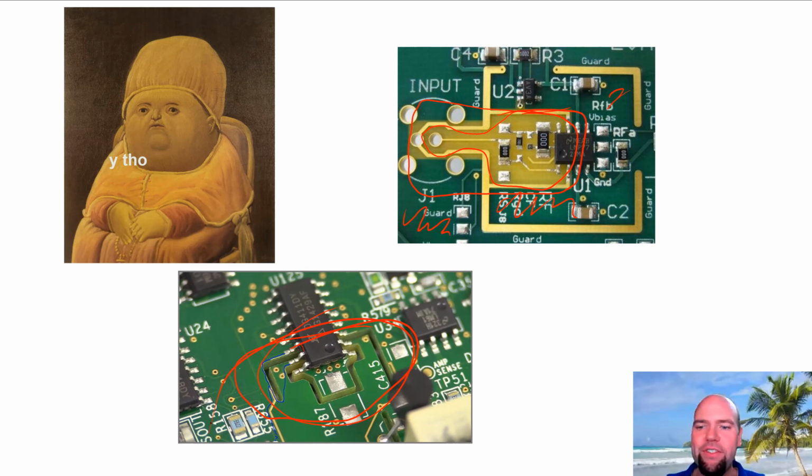If you're really worried about these stray resistances, if you really want to use a gig ohm resistor, you're going to have to play games kind of like that. But they still pick up a lot of noise. They're still just not advisable.